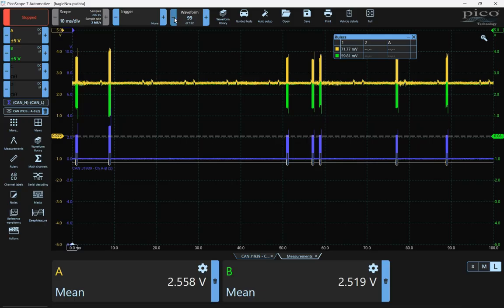So within the loom, this was where our problem was. We took it apart. We were able to pull the wires apart and separate them and wrap some black tape around them for the time being. Ordered that section of harness. I mean, it was pretty cheap. It was a couple $100. It was a fairly simple harness. And in the time being, we were able to get the customer back up and running and then replace that section of harness.